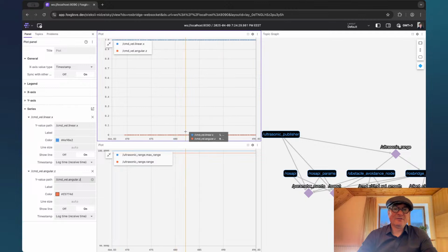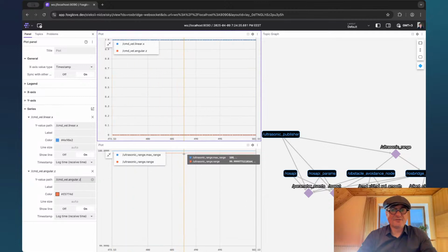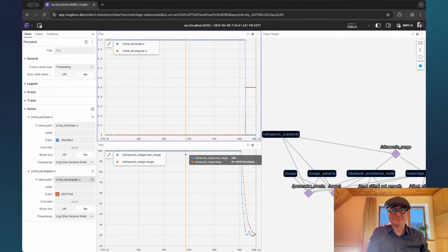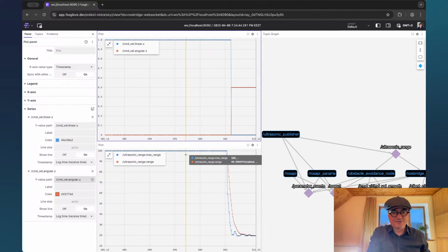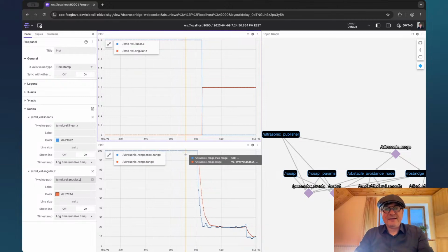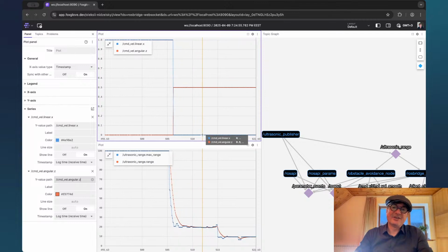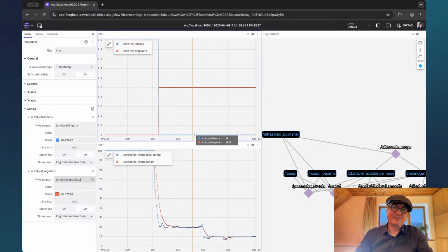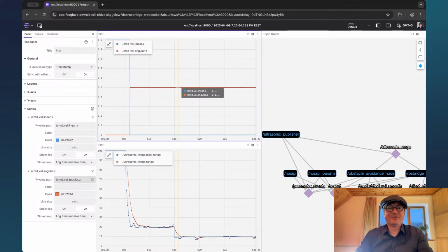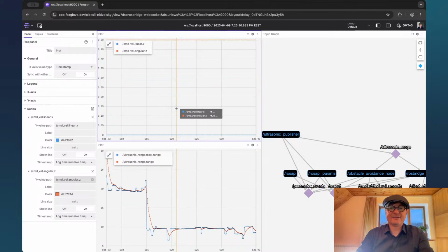And now we see linear X equals 1 and angular Z equals 0 because the distance is 100 centimeters. But if we decrease the distance, for example, now it is approximately 20 centimeters, we see that linear X becomes 0, so the robot stops moving forward, and the orange line angular Z becomes 0.5, and it means the robot starts moving to the right.